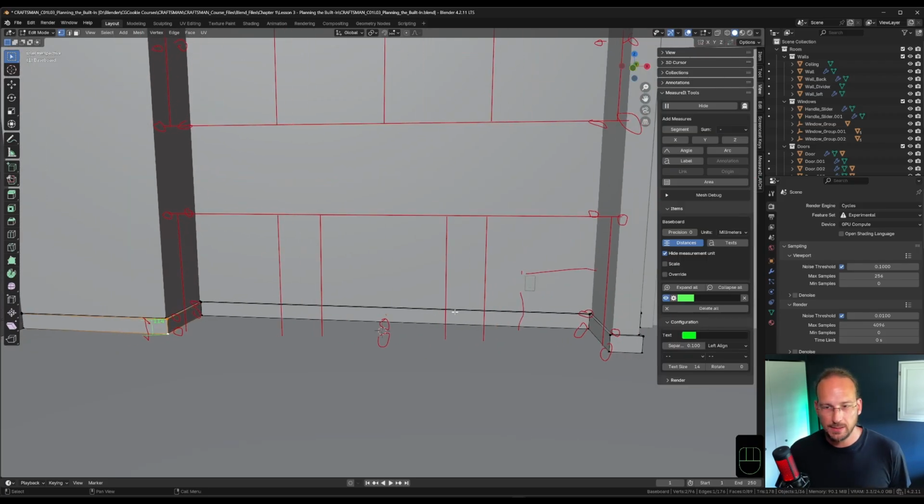Now in this case, because everything's going to be closed in and none of this will ever be visible again, I talked to the client and we agreed that we just take the baseboard out in the back. And that way we eliminate the problem. And on the sides, because we have the trim panels, we can just make a notch around the baseboards and that way we won't have an issue there and the kick can be fit in between.